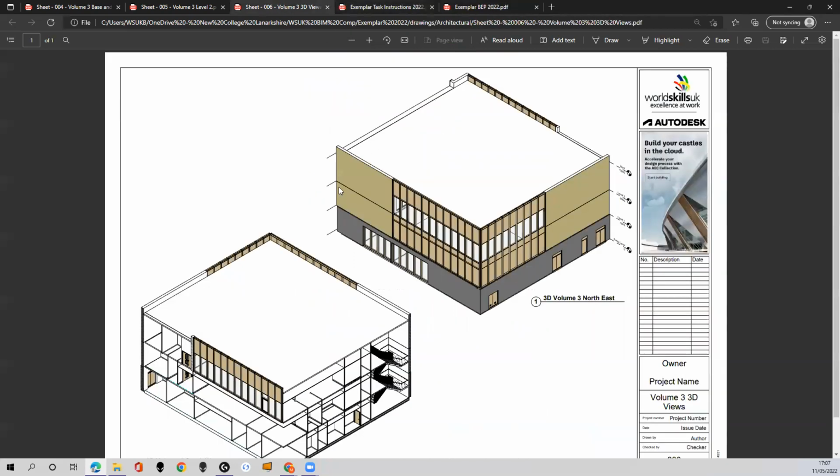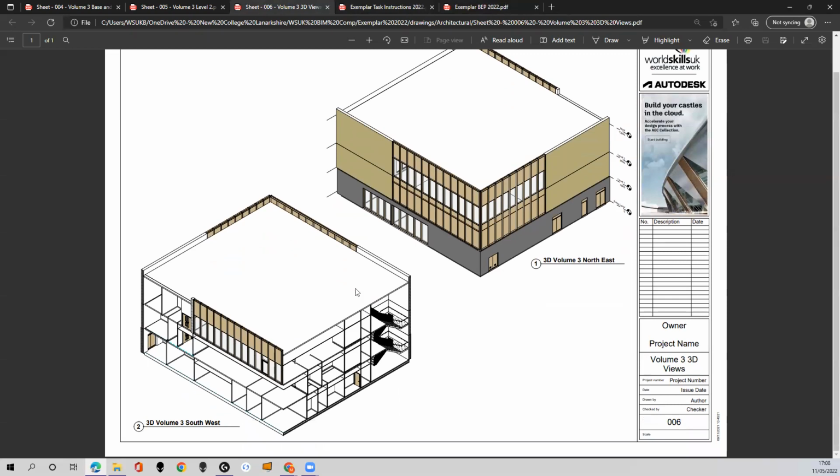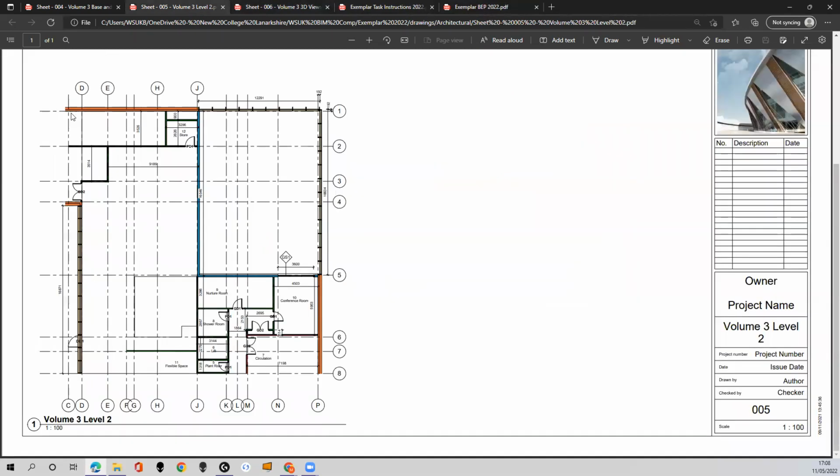So typically, you'll notice this, it's not got 4 external walls. There's external walls missing to the side. And in plan view, you would just use the grid line to define that. There we go. So if I was drawing a roof, I would use grid line C to define where the edge of the roof is, for example.